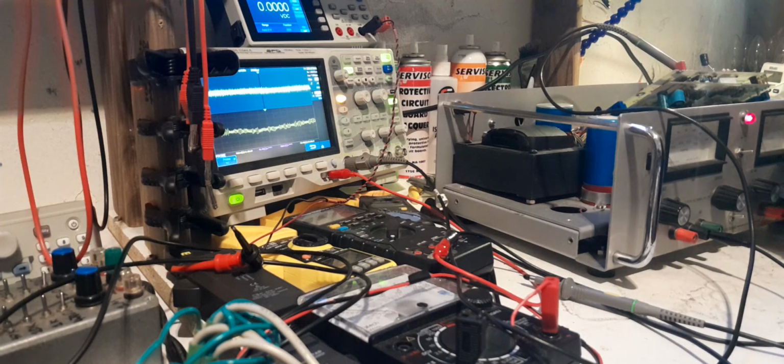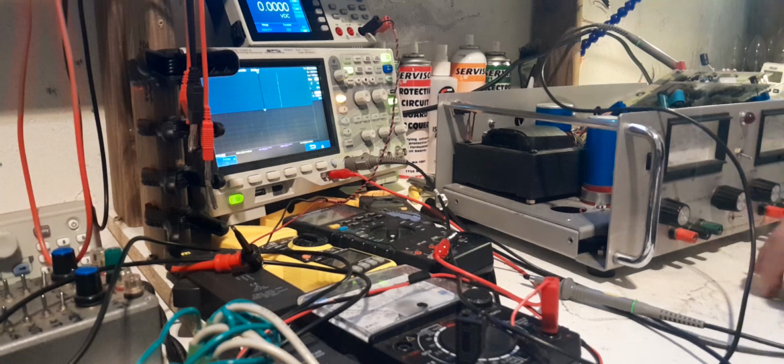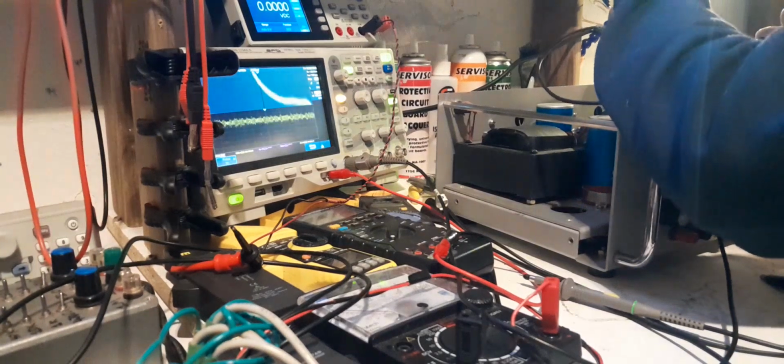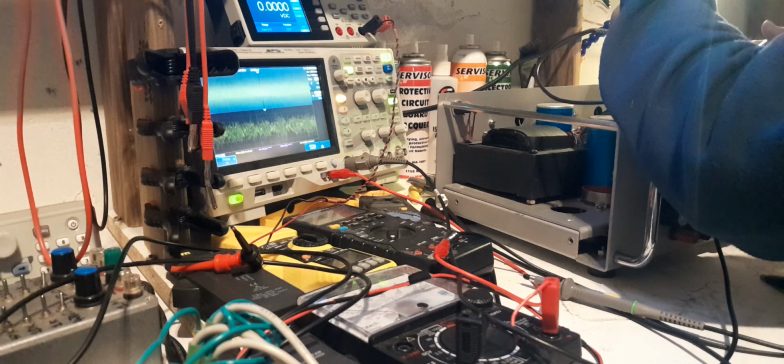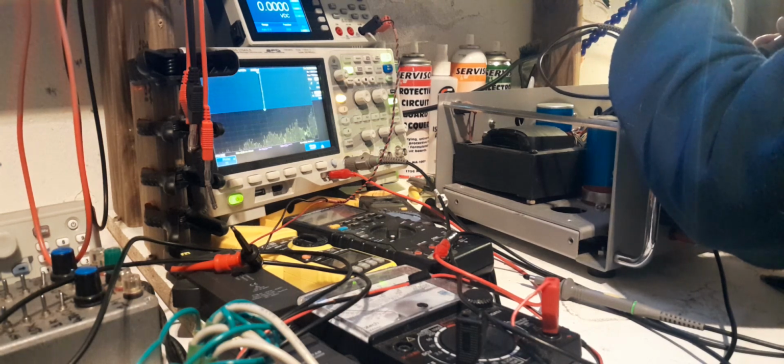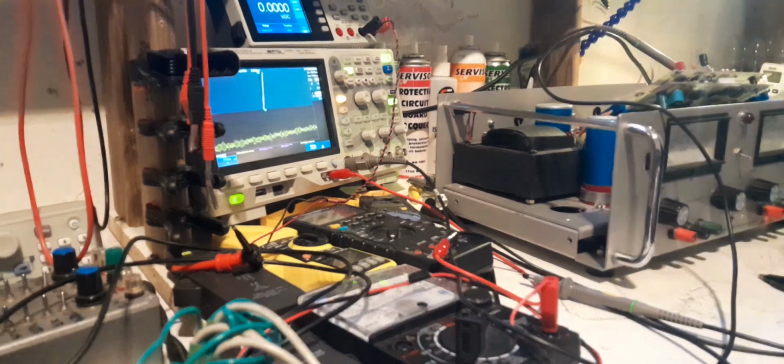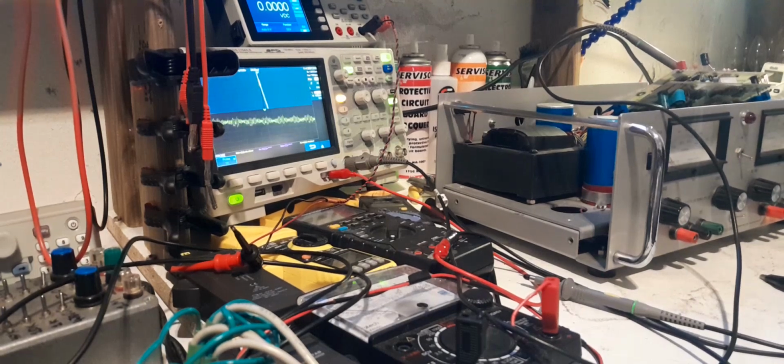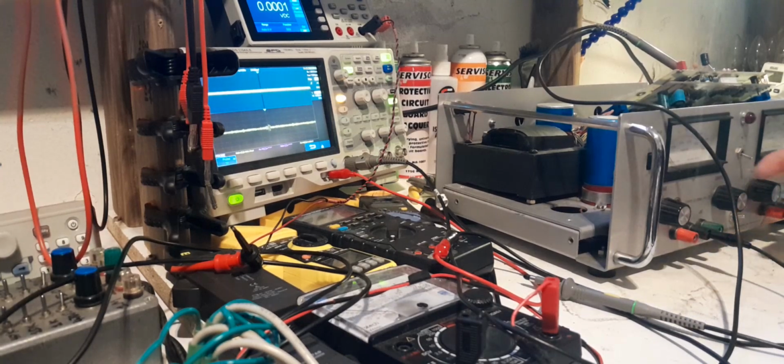Now I'll just take in my hand, in between the output, and you know what, I'll solder it. Between the output and the non-inverting input, I'll just put a 100 nanofarad capacitor there. I know it's a really big value and it could couple mains noise into it, but I'm sure for the educated people here, including everyone that's probably watching this channel and myself, we'll know if we see mains ripple compared to high frequency noise. So, not really worried about that.